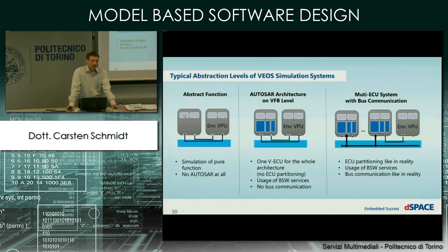Okay, then we have a second phase where you may have implemented all these software components, but where you don't want to worry much about the actual ECUs. For example, you have not decided what software component should be placed on what ECU. You have not developed your bus communication matrix and so on. So you only want to simulate a set of software components, so your software architecture, on a quite detailed level.